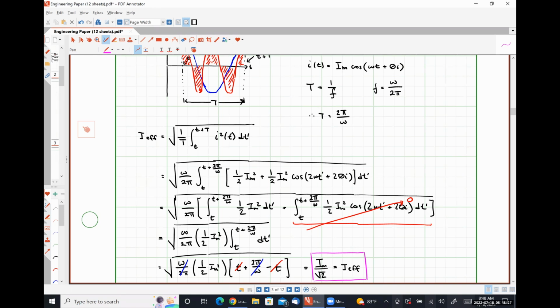In most parts of Europe, their voltage distribution oscillates at a frequency of 100 pi radians per second. So two different frequencies. However, the analysis required to determine the effective value and use the effective value quantities is exactly the same. It's simply the magnitude of the sinusoid over the square root of 2.